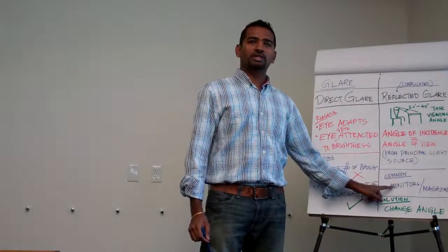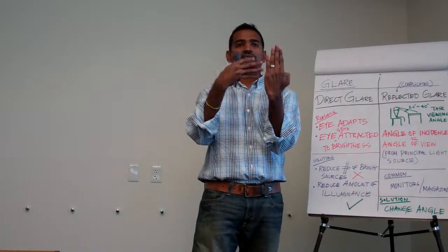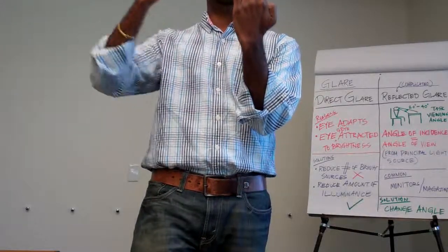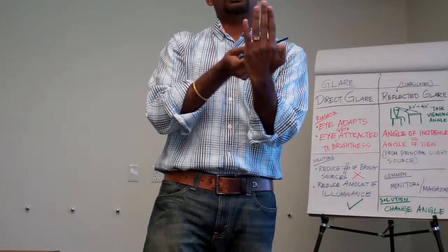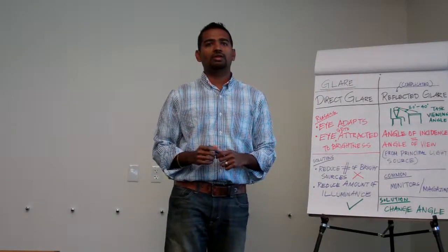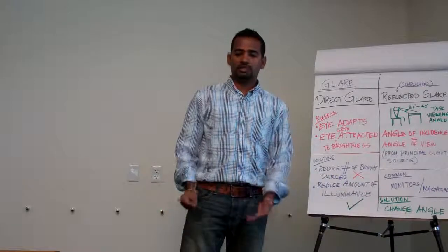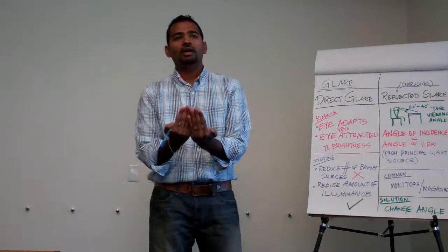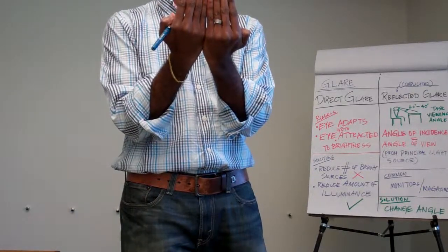The other veiling reflection issue is on a monitor, right? The monitor is usually pretty reflective, and that's why we go to non-reflective monitors. Reflective monitors usually reflect the light source back at you, so you can't really see anything on the monitor. That's why it's important to plan the office layout and understand where the monitors go when it comes to downlighting. The simple solution is, if you have veiling reflections on the magazine, just tilt the angle and you're good to go. But if you tilt the angle and you don't receive enough illumination on the magazine, can you still read?